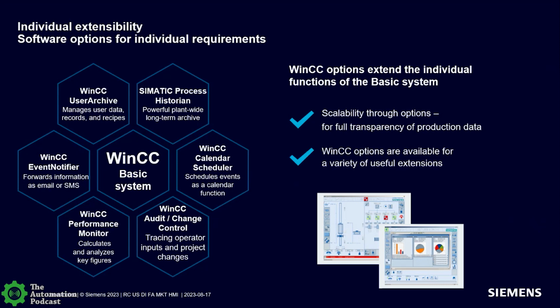We also have WinCC audit and change control. So if you're in an application where you really need to see what's going on because it's critical, like FDA applications where you're making something and you validated the machine and says, hey, as long as I don't change the parameters, I'm making good product. You've got to keep track if you're making changes. So audit will do it in the runtime world. We'll keep track of any operator changes or operator inputs on whatever values you define.